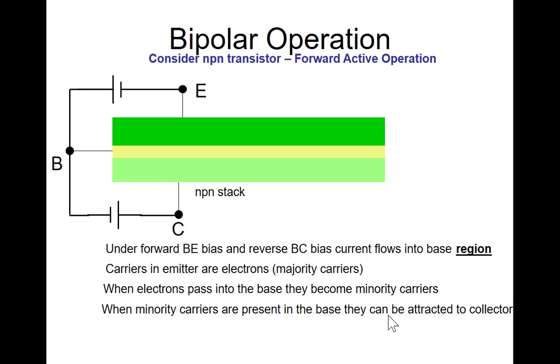We're not applying a positive and negative voltage to the base. You can think of this as ground if you want to for the purpose of this illustration. So I'm putting a negative voltage on the emitter and a positive voltage on the collector then. Good question, but I'm not providing two separate. If I connected these together, then we'd have a problem with Kirchhoff's voltage law around the loop, but I've not done that. Good question.